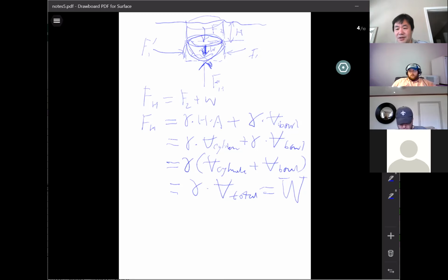Okay, but not everywhere, just exactly on top, vertically on top of the bowl surface. Does that make sense? Everybody, is that clear? Okay, so the reason I go through this is we start with a very complicated engineering concept, but eventually lead back to a very, very common sense idea. The force on the surface of this bowl is just basically the total weight of water sitting on top of it.